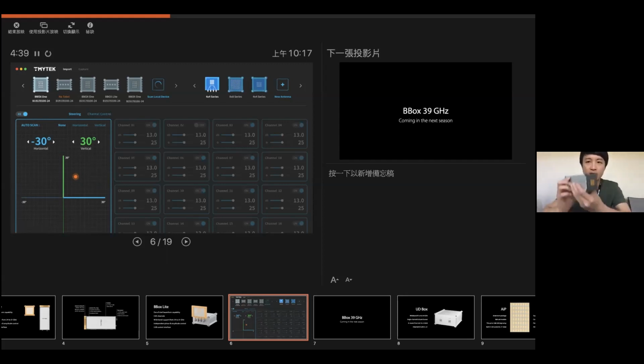What BBox is receiving, the power will come up to here, the COM port, right? So if you want to know what power is being received, we need to measure through this port. That's the RF COM port of the fully functional beamformer. That port can be used for either TX or RX. It's bidirectional, there's no problem.